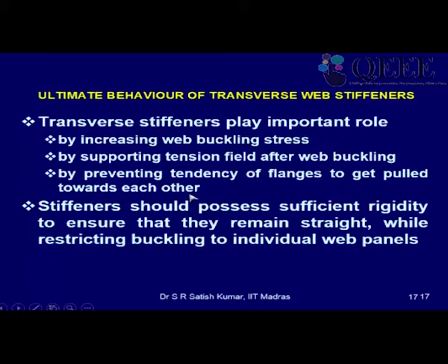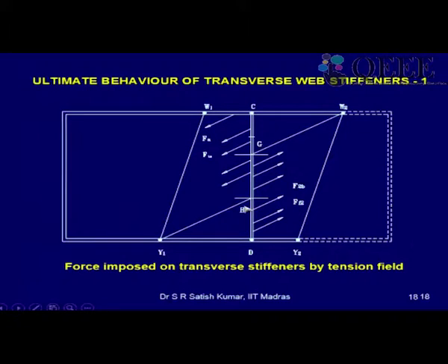So they basically play three roles, and to play these three roles, the stiffener should possess sufficient rigidity to ensure that it remains straight while restricting buckling to individual web panels. So stiffener design becomes very important. Okay, this shows how the stiffener is cutting the aspect ratio.